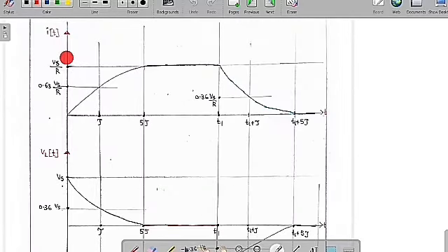So if you know this value, you substitute here, you are going to get the value of VR(t). So now I am going to draw the diagrams of current in the inductor and voltage across the inductor with respect to time, for charging mode and also the discharging mode. Current in the inductor cannot change instantaneously, so it is going to increase in a very slow manner in the charging mode. The initial current is 0 because it is an open circuit. We have assumed the current in the inductor is 0 initially, so this is 0 at t is equal to 0.